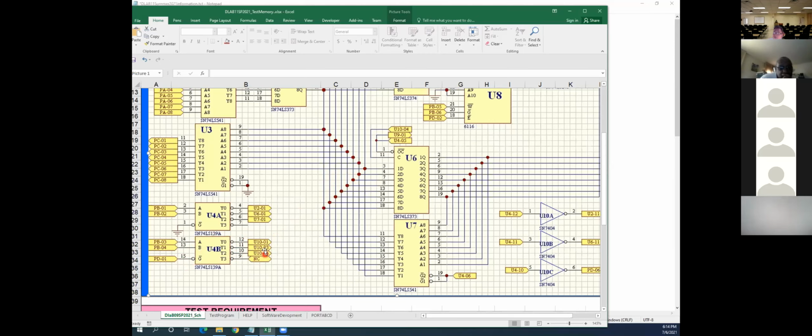The thing is the output here will create the port output at U10. If you route it, then you cannot get any ports coming out here. So that's why every time you want to latch, you have to apply PD pin 1 as 1, then 0, then 1. Because when you have a latch, you want to have the door closed, then open the door, let the data in, and then close the door again.